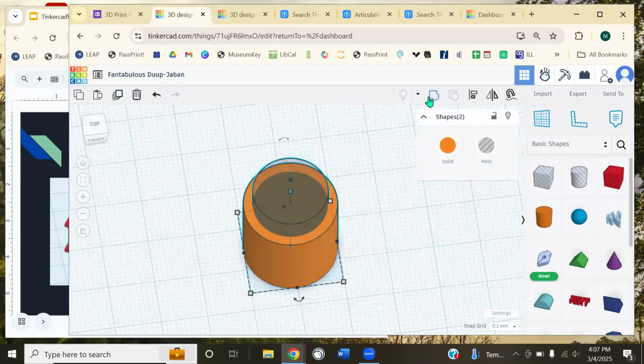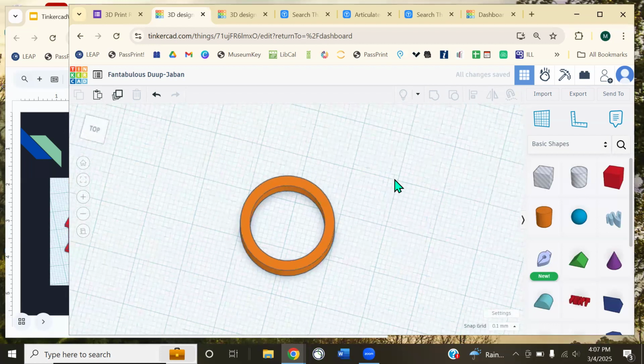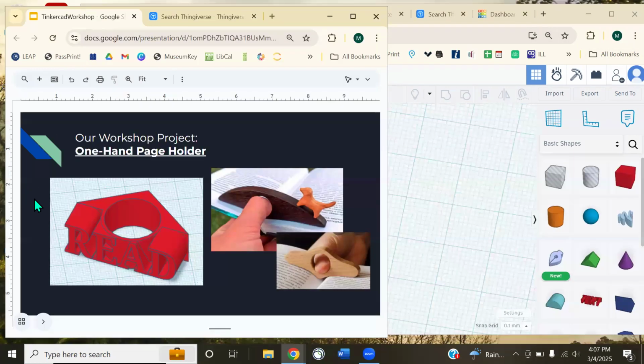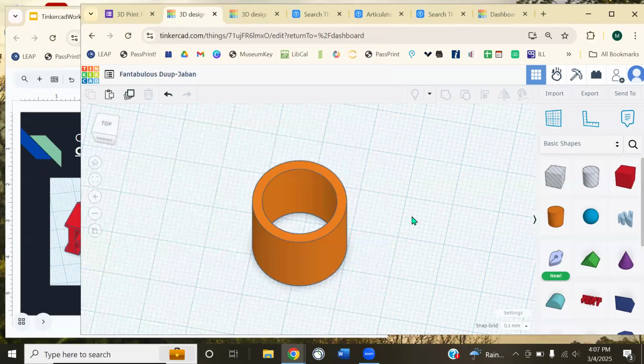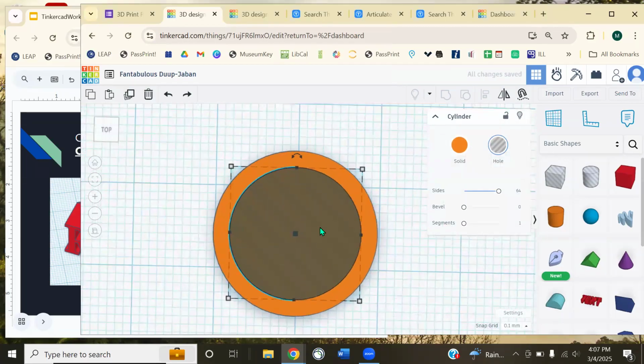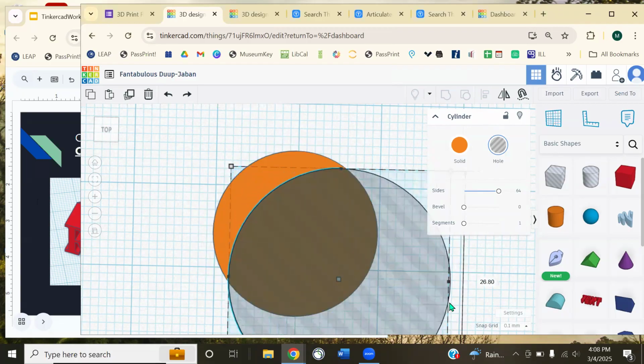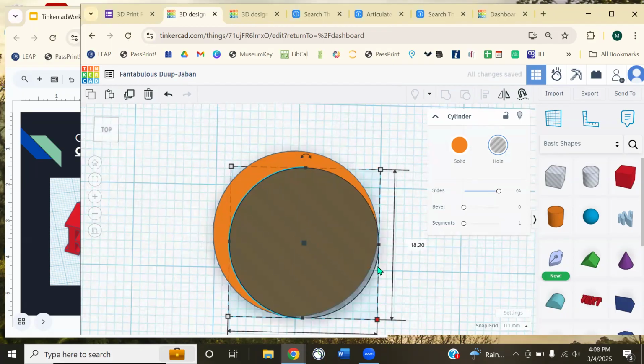You can come back to that group tool, also Control G if you want. And then you can see we get it exactly cut out like that. If we want, the model that I might be trying to mimic is quite a thin wall. So maybe I'll undo that real quick, and maybe I just want to scale the hollow bit out a little bit so it's not quite as thick. If I hold down my shift key, you can see it's going to scale it up relative to the top left piece of the object.